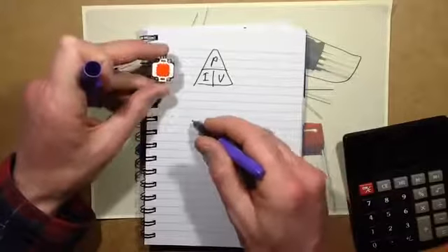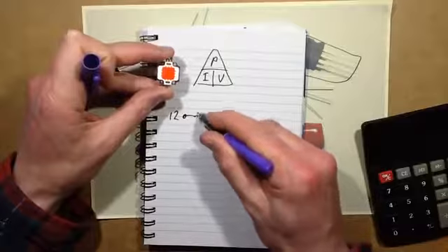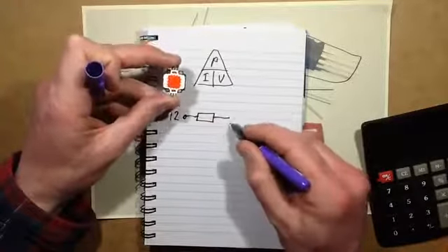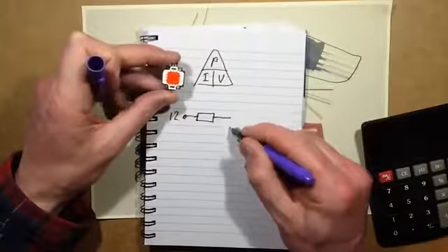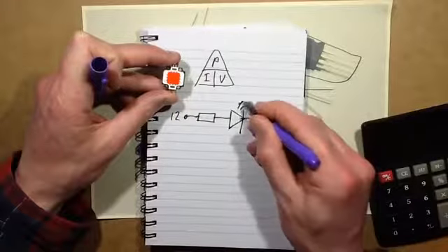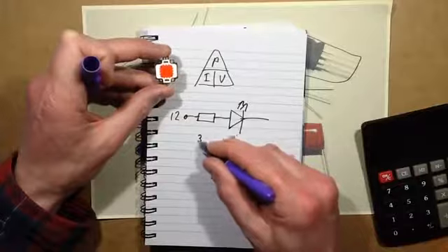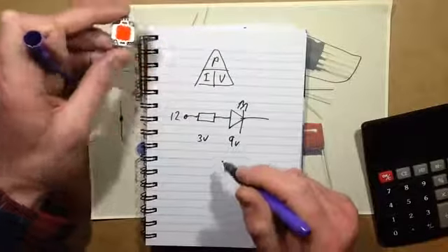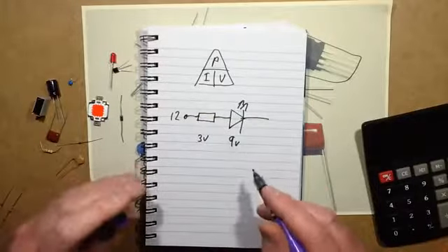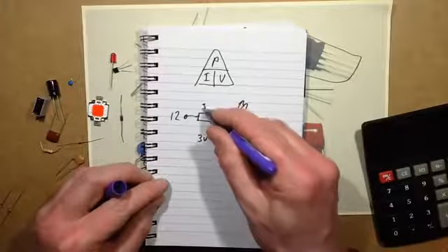So to calculate, if we were to actually put a resistor at 12 volt supply again, and choose a resistor to limit the current through this to the 1 amp. So let's see, I'll just draw it as a huge big LED. I'm not going to draw what's in it. There's a 3 by 3 array, but the voltage across that is about 9 volts. So we've got 3 volts to drop across the resistor. And if we go back to the original formula, R equals V over I, we've got 3 volts divided by the 1 amp we need, so that's going to be about 3 ohms.